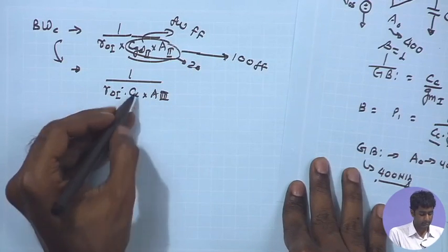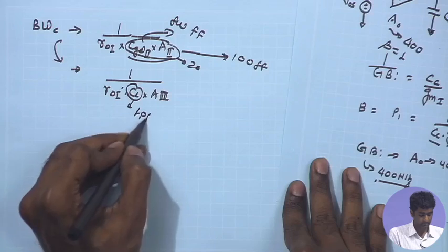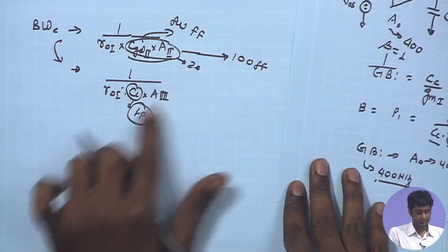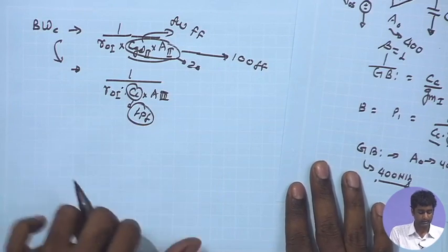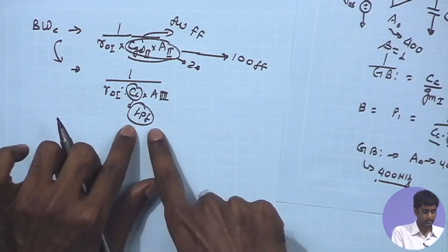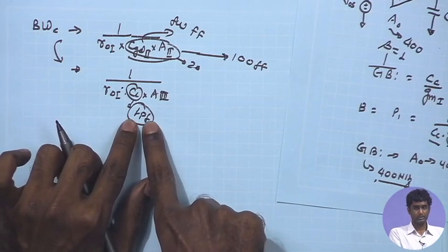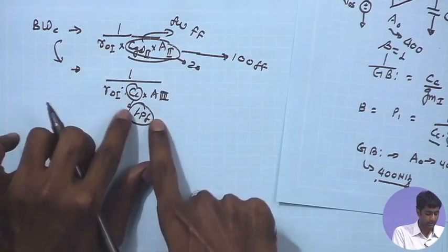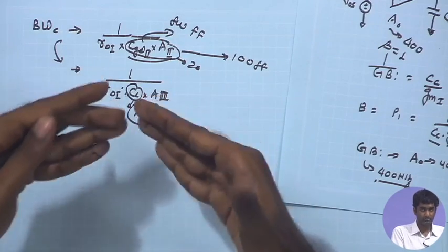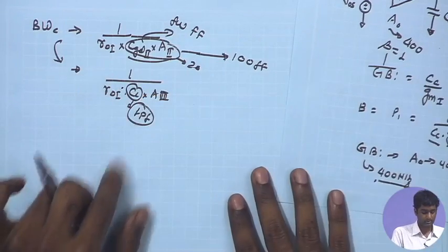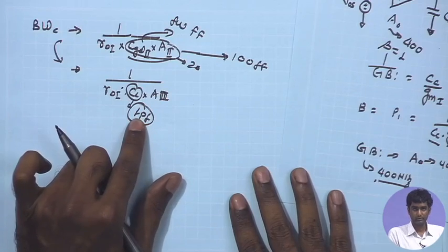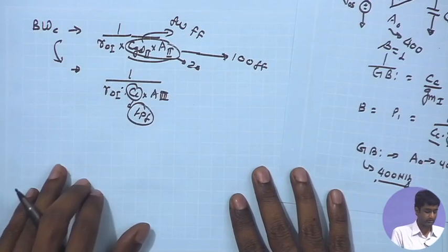Here this value we have chosen 1 picofarad, right. So, of course, the capacitance has gone up by 10. As a result, if I am looking at the open loop bandwidth, as compared to that, the open loop bandwidth of this voltage follower definitely is lower by this factor of say 100.